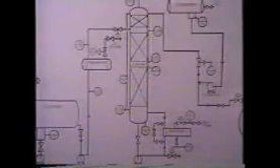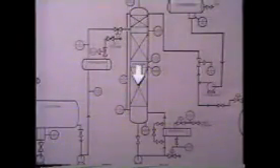Once heat to the column is stopped and the column cools down, the vapor will condense, flowing down the column and mixing with the bottom's product. Resetting the bottom's takeoff flow controller to 0 stops removal of the bottom's product and prevents any contaminated product from mixing with the pure bottom's product.